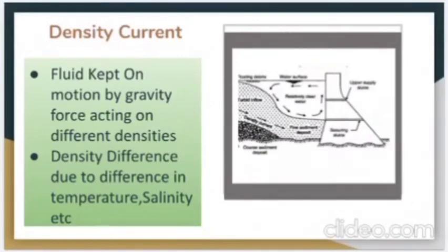Density currents are of considerable practical importance. For example, the deposition of sediment from turbidity currents, that is density currents in which the density difference is caused by the suspended sediment in lakes, may result in a rapid decrease in reservoir capacity. The rate of silting in a reservoir can be reduced if the density currents are vented by the proper location and operation of outlets and sluice gates.